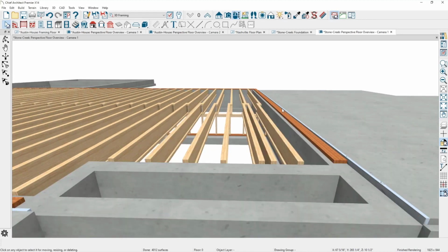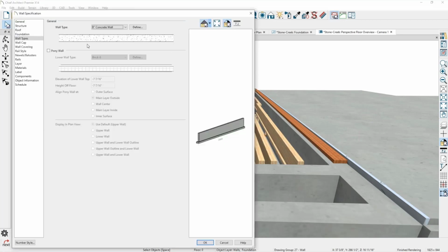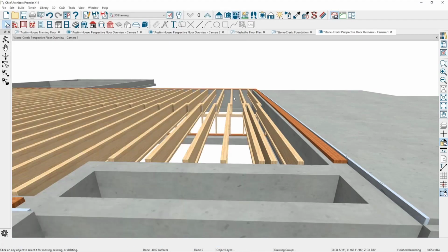Right. So I don't necessarily have time to go through and change all of this, but what I ended up doing is modifying the wall so that it's not hung, step one. So I would build the foundation so that these are not hung walls. I'd remove the check mark down here that says it's hung. Then those floor joists are stacked on top of the concrete wall. Effectively, that's going to raise this floor up on the left-hand side of the structure 15 inches.